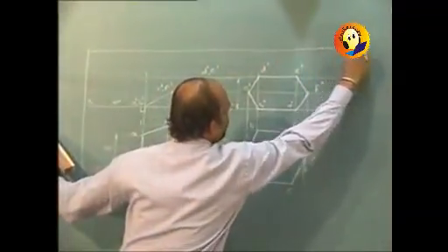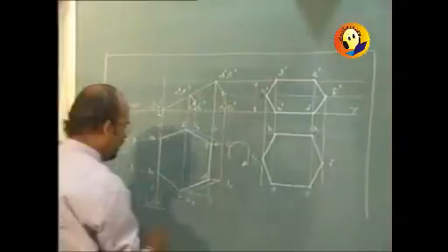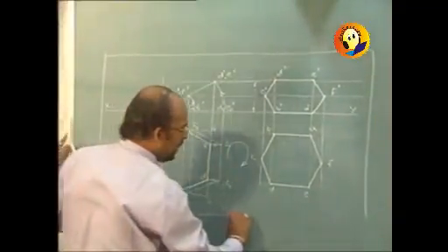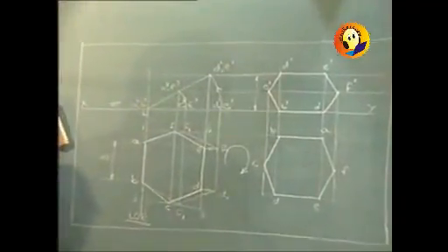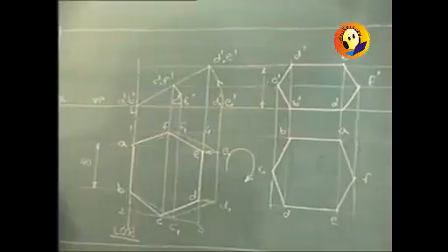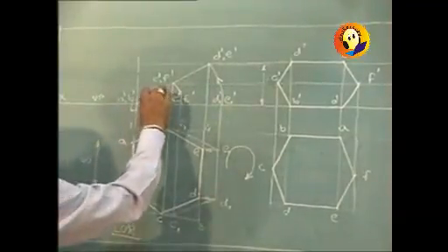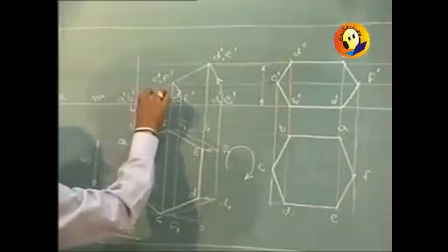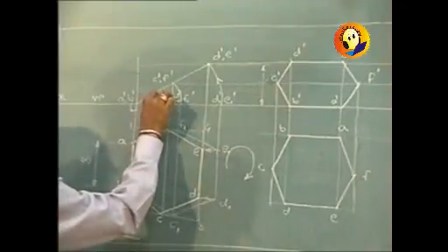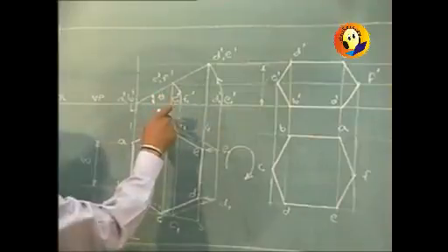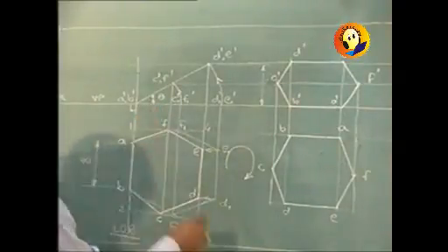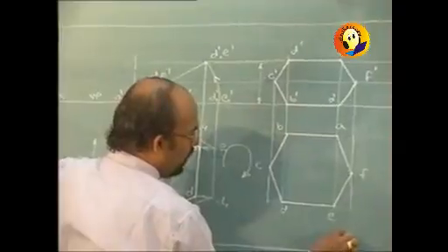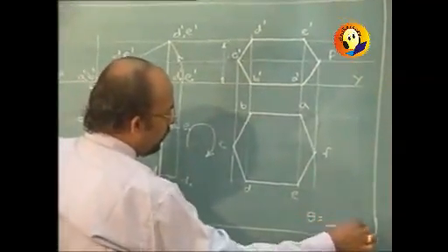And in all these 4 problems, we have dealt with only the case when one side of that polygon was resting on HP, and that itself was the line of rotation. Again, in this case, the angle made by the plane with HP, that is angle theta, was not given to us. So the last 2 problems, this and the previous one, are the cases where the angle made by the lamina with HP was not given to us. We had to find it every time, and you are required to also write the answer by measuring that angle.